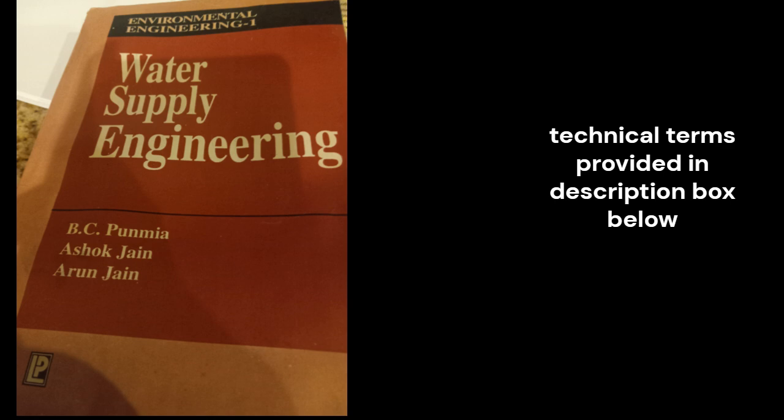Those are the stages here. Then the next is design of mechanical rapid mix unit. It has first step, design parameters. Second, determination of dimensions of the tank. Third, computation of power requirements. Fourth, determination of dimensions of flat blades and impeller.